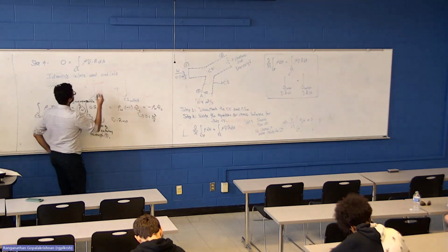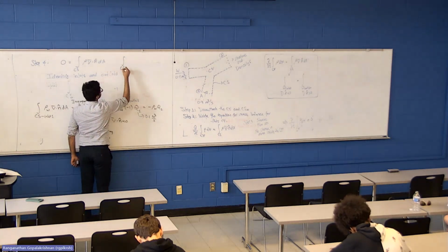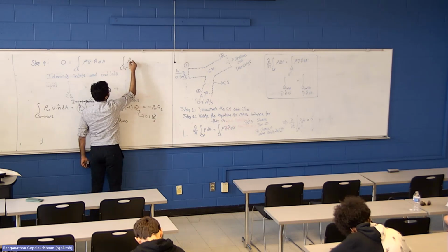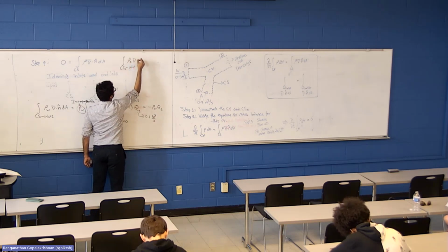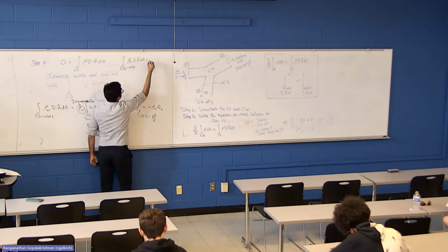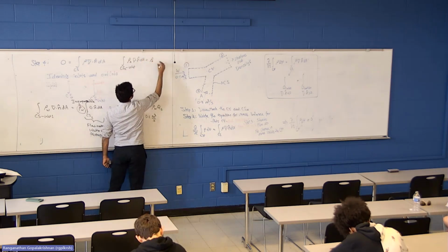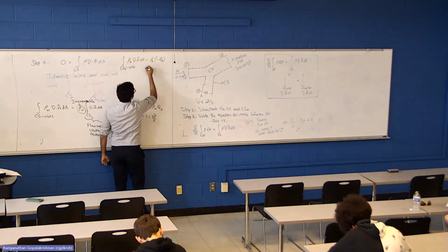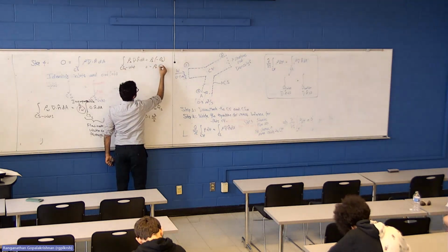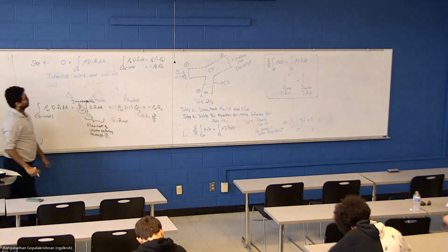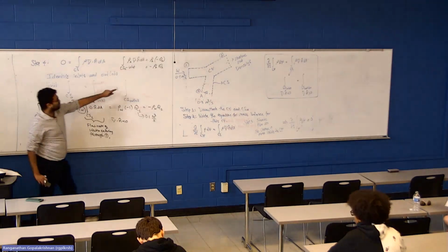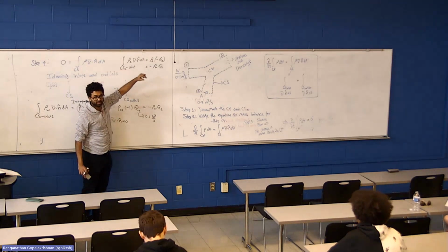And what about inlet 2? If I write this for CS2, which is again another inlet, I have rho alcohol times V dot N dA, that is equal to rho alcohol multiplied by minus Q2, or this is minus rho A Q2. The main thing I'm adding is whenever it's an inlet, I'm adding a negative sign so that the math will work out correctly.